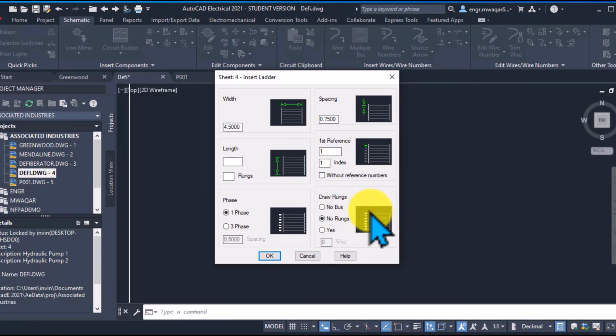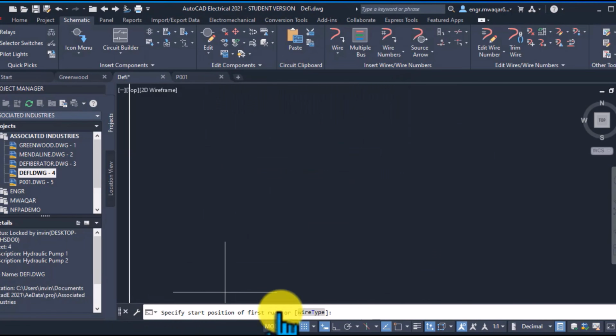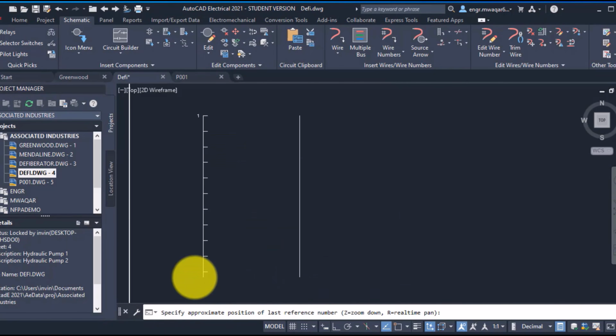No, it won't create a rung 10.5 just because you click there. It enforces the grid you established. So you simply can't force it to violate its own structural rules. Exactly. If you need space, you have to move things first. You have to use the scoot command, which we'll definitely get into later, to physically push the existing rungs apart and open up a mathematically valid slot for the new rung. It really forces you to maintain drafting standards.